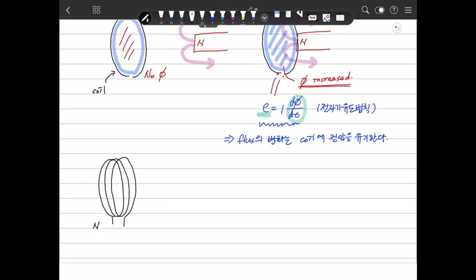In the same way there is the magnet, then the flux happens in this way. Because of this flux, d phi over dt induces the voltage. But there are n turns, and each turn has a voltage in this amount. So the total induced voltage e is n times d phi over dt. This is the final form of the Faraday law.